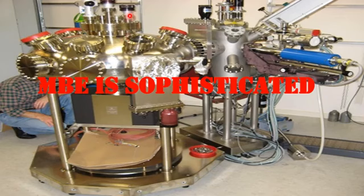There are many more techniques, like SEM or TEM, which are different types of complicated setups also associated with molecular beam epitaxy. So it depends on the limitation of the available device. The disadvantage of molecular beam epitaxy is basically the sophistication. This setup is sophisticated because it is quite difficult for molecular beam epitaxy to achieve a vacuum pressure of 10 to the power minus 8 to 10 to the power minus 10 torr. This pressure is too high.